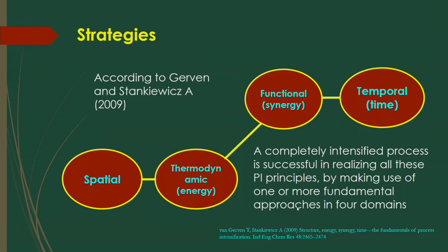And also, in a particular chemical engineering process, higher residence time sometimes may hinder the process output. So, for some particular processes you need to have less residence time of the fluid. For other processes you have to design the process equipment in such a way that for longer time the fluid element stays inside the column.